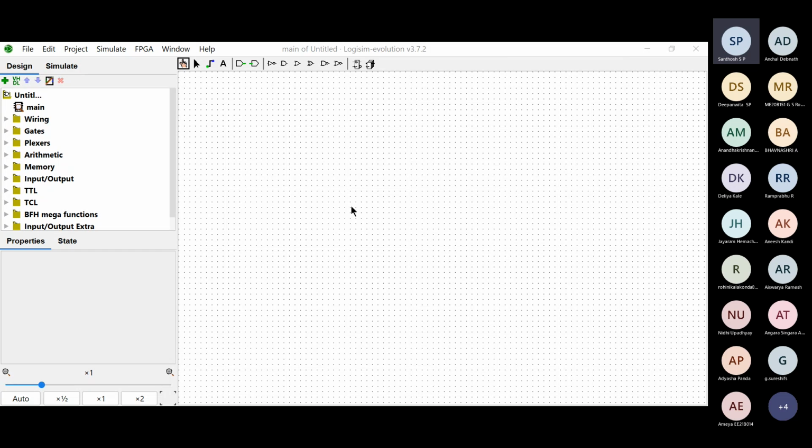Yeah. And then we can move to the truth table. It automatically generates this table with all the possibilities 0 0, 0 1, 1 0, 1 1. So we just have to click on these columns. We have to edit this to get the required truth table for the half adder.